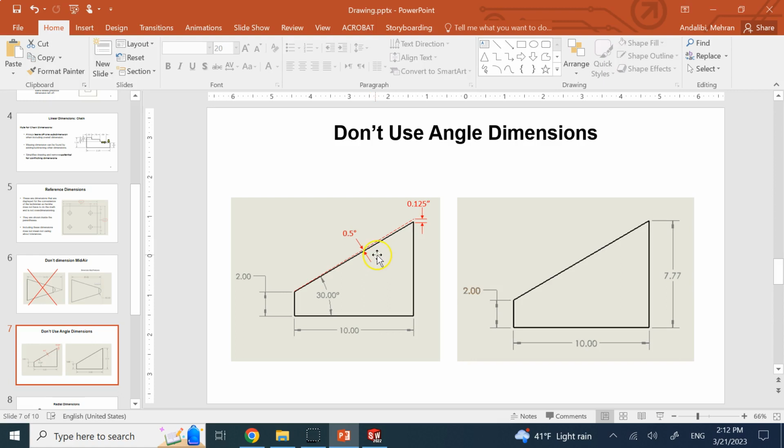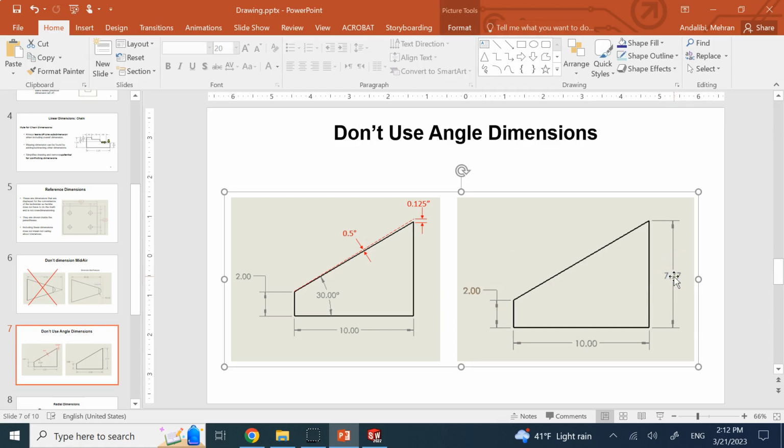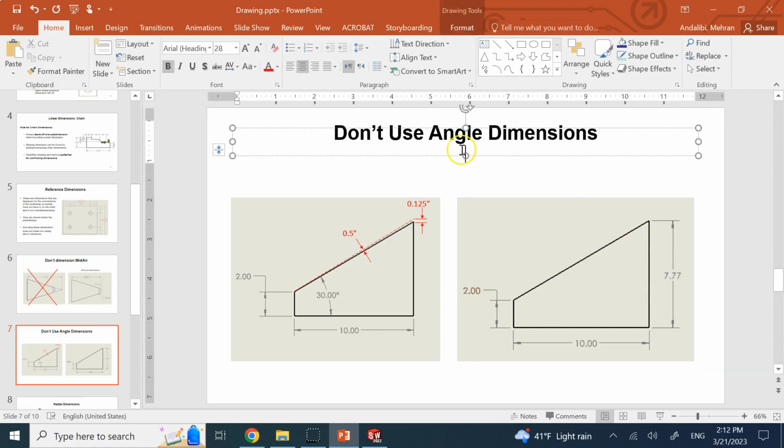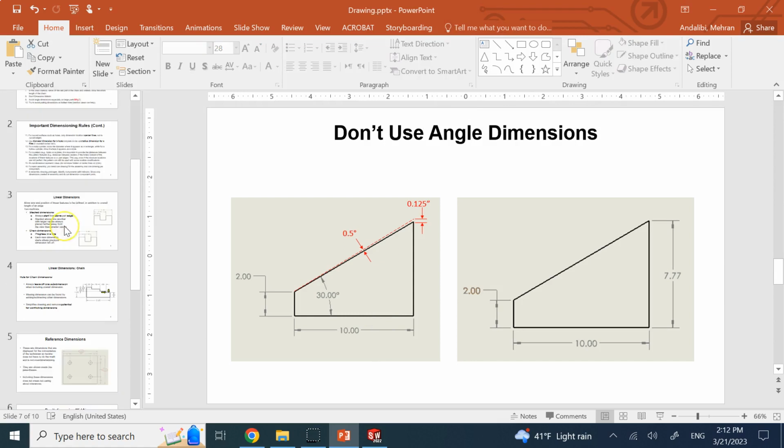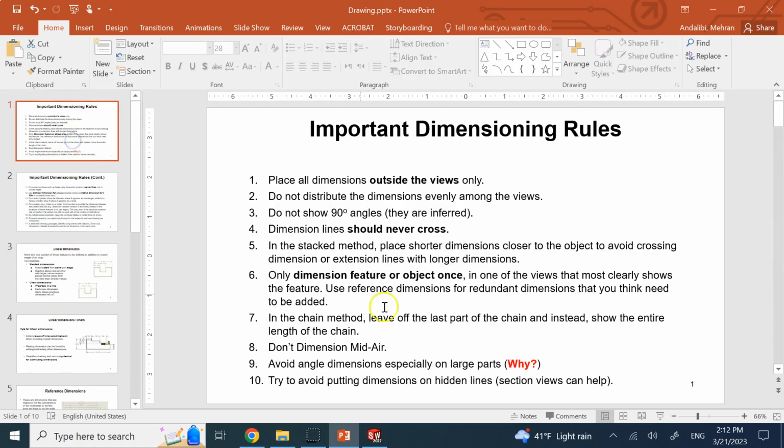So with most devices, you cannot go below 1 degree. You need very, very accurate devices in machining to be able to have tolerances for angles that are only fractions of a degree, very small fractions, but fractions of inches are very common. So in general, angles in large dimensions are not the best idea.